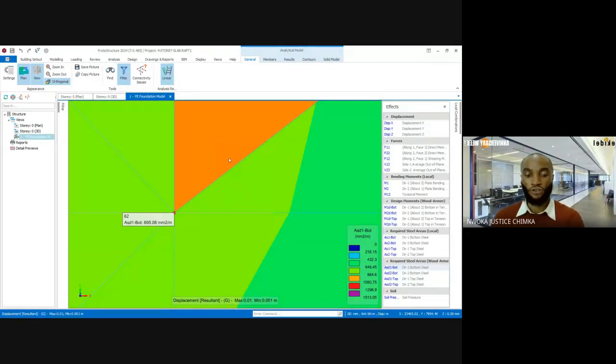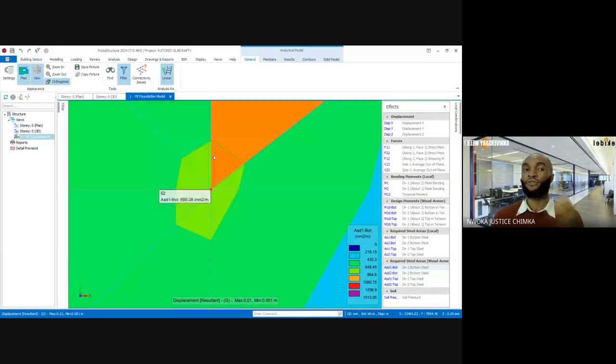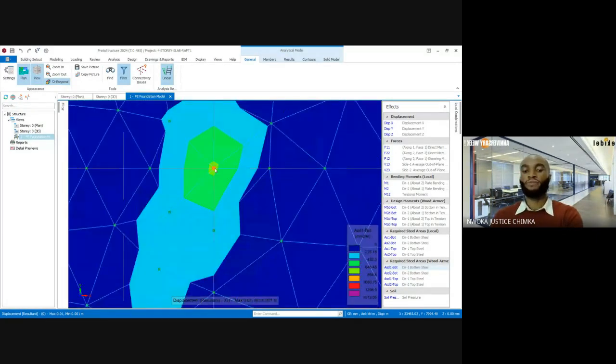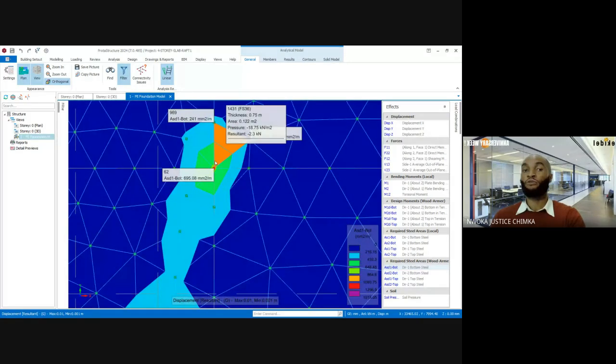So on this column, the only contour here is this light green yellow, which you have already factored in. That's what we used for our general marking. That means the general marking can carry the load from this column, so we will leave this column from punching because it doesn't have any punching issue.